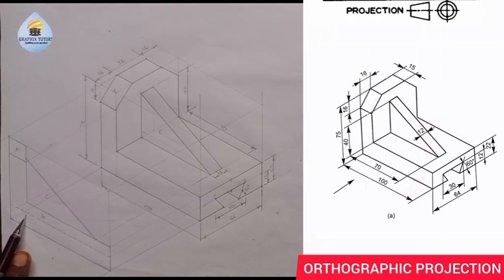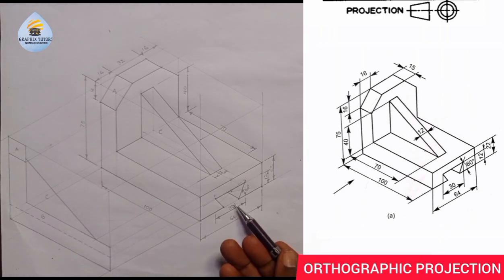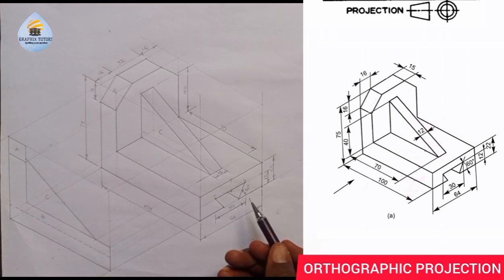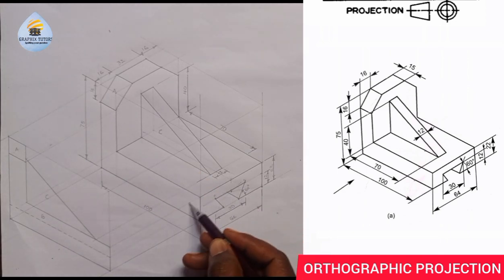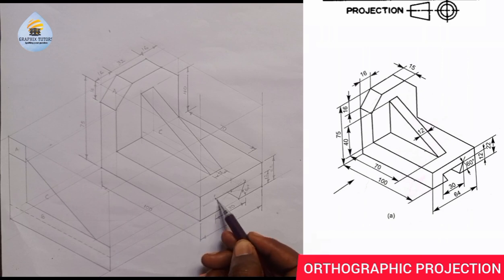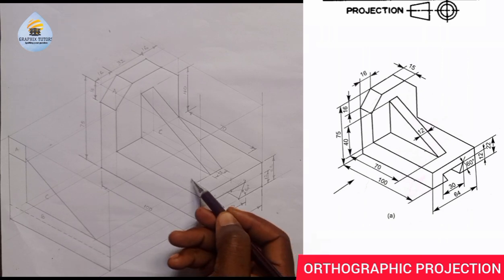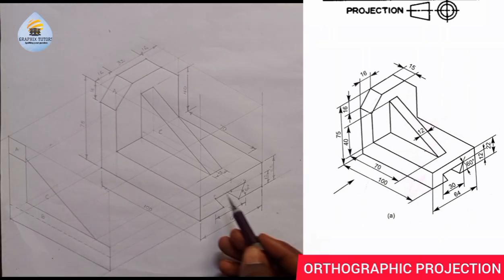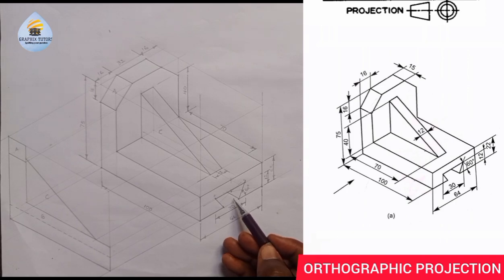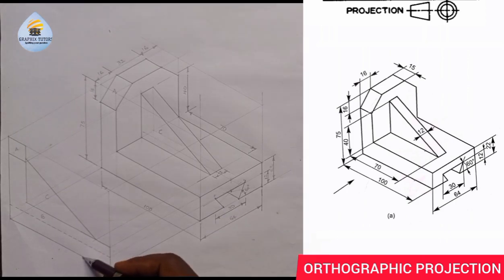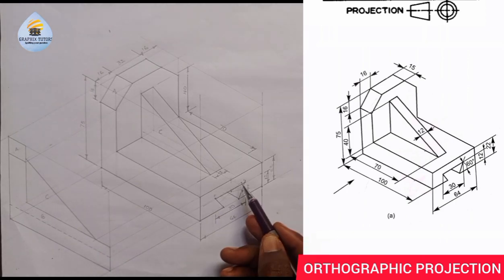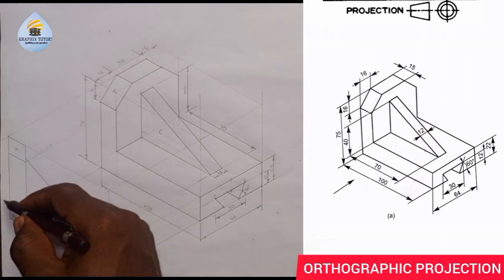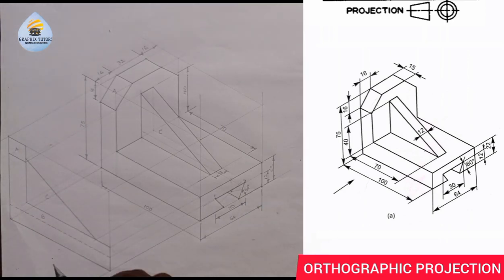Now what do you notice? We're seeing an inner line, meaning that there's a hole, a through space in between this figure here. And from here you cannot see inside here. So to show that there's a space in between, use a hidden line to show the hidden features here. So all this space you see is all this space here, while this line, which is blocking this line, is this, which will be seen as a hidden line. So this is the front elevation.